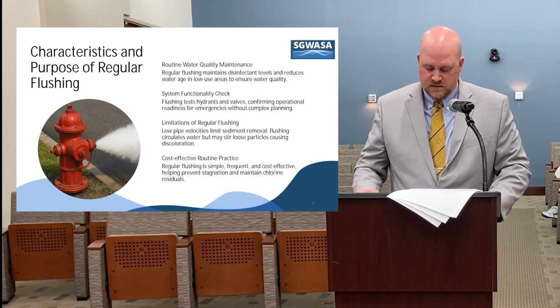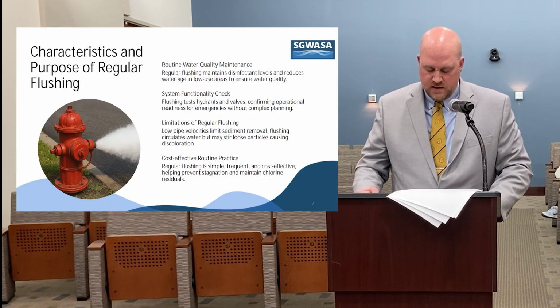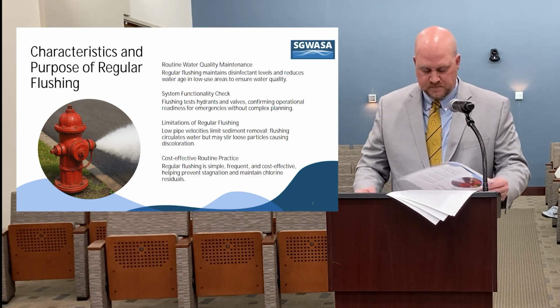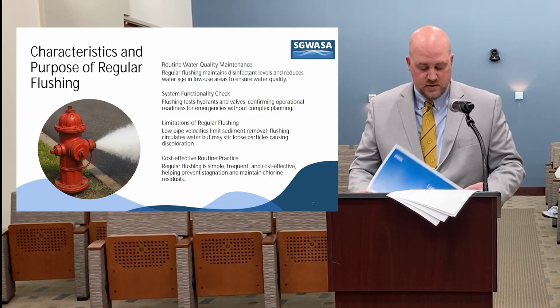And this is a cost-effective routine practice. So regular flushing is simple, frequent, and cost-effective. It helps reduce stagnation and maintains chlorine residuals. So that's regular flushing. Unidirectional flushing.